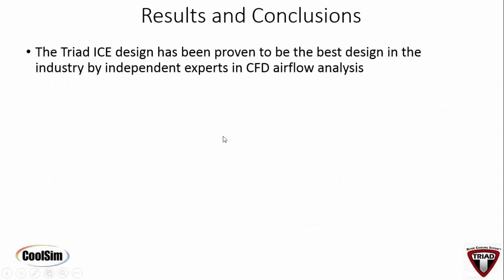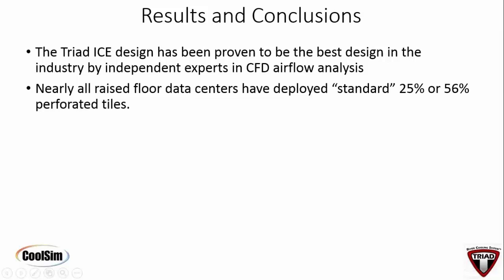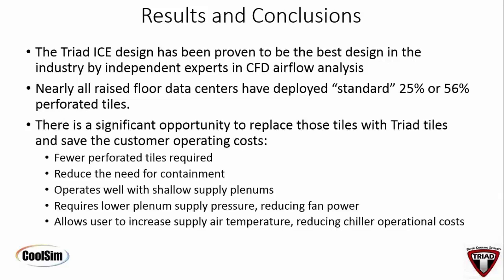Right. So it looks like the design, I don't know how you came up with it, Gary. I really don't, but whatever you've done here, it's working. It works better than anything we've looked at. It's better than the 25 and 56. And there seems to be here a good opportunity to use fewer tiles with shallow plenums. I run into a lot of data centers that are 18 inches. I mean, that's not uncommon. If we're lucky, Gary, we find them at 24, right? Mm-hmm. Right. So you don't need to.